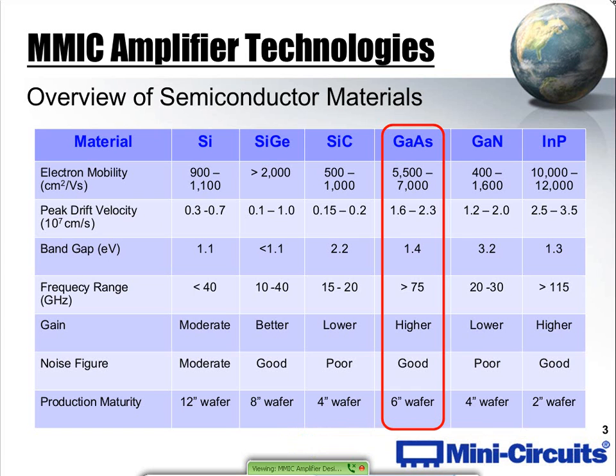So silicon has its roots deep in our industry, but it's also an ongoing force for RF and microwave solutions. The other thing about silicon is you can get extremely large format. 12-inch wafers are common both at IBM and TSMC. So in a 12-inch wafer, you think about the scale, the number of chips I can get per wafer, and that really drives the cost. So silicon, from a cost solution on a per unit basis, is extremely attractive. That's why you see it in use in mobile devices, set-top boxes, handsets, and really dominating the industry.